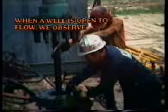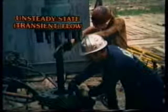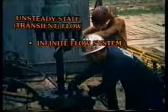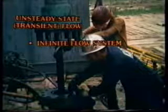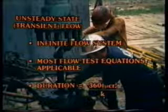If this is done, we may observe 3 states of flow: unsteady state or transient, pseudo-steady state, and transitional. Unsteady state flow occurs during the time when the flow system acts as though it is of infinite extent. Most flow tests are applicable during this period.